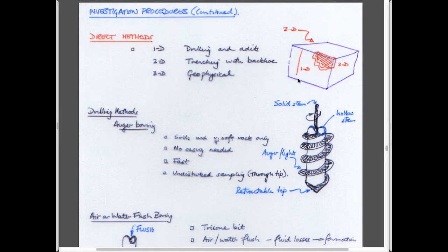And if you want to look at the three-dimensional picture, short of being able to excavate everything, in which case you've destructively destroyed your site, you can't do it unless you use geophysics. So there's this kind of interaction between maybe drilling a hole, maybe doing some geophysics to correlate what you see in that hole across the rest of the site, and then depending on what you find in the geophysics, maybe drilling some other holes in other places that give you confirmation of some things that you really want to see.